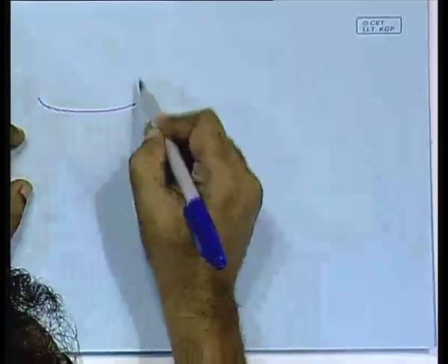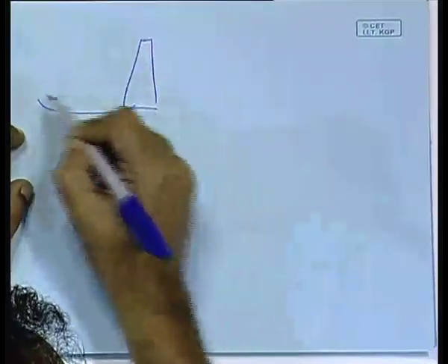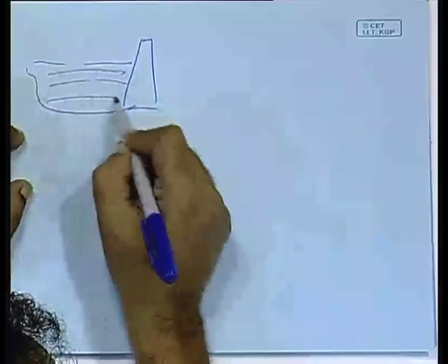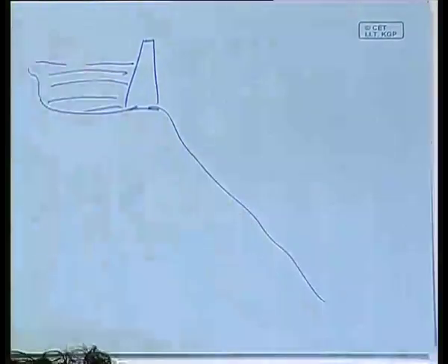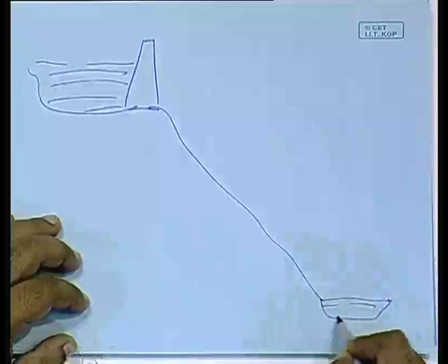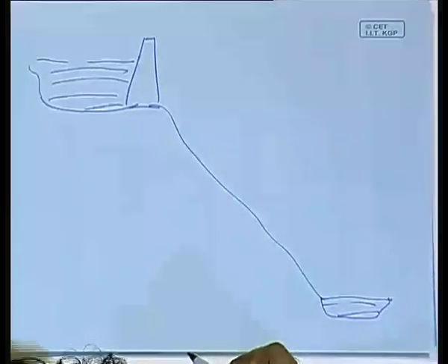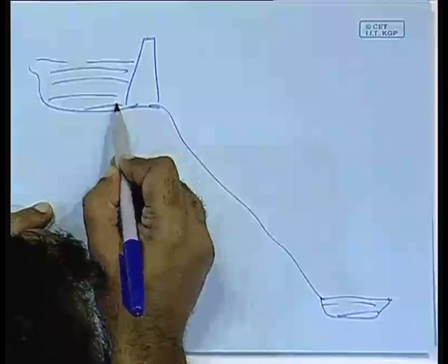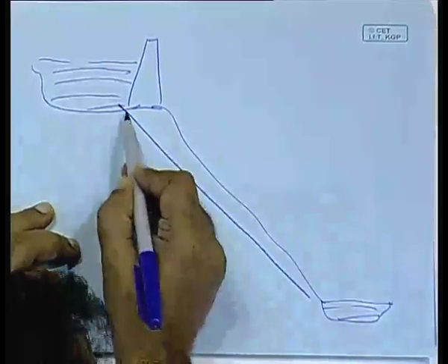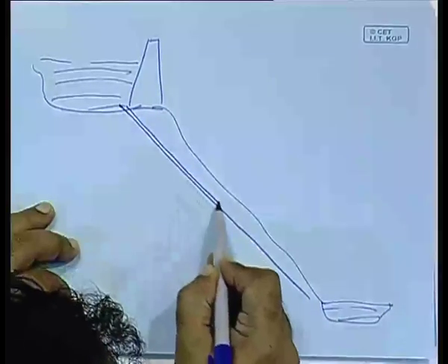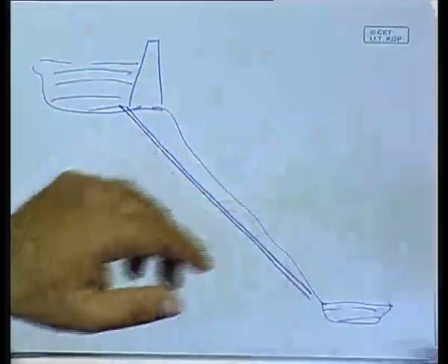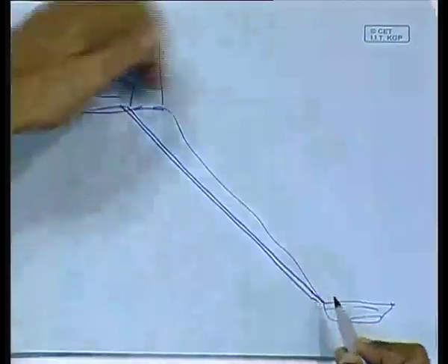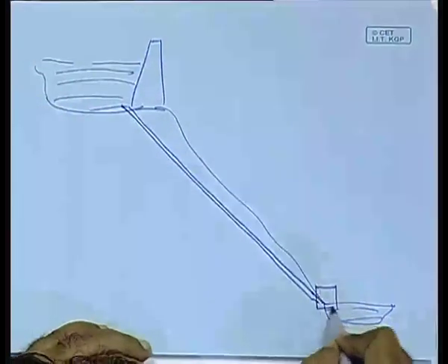Okay, before we end, let us again look at the structure of a normal power plant. There would be, in the upper reaches, some kind of a reservoir. So here you have the reservoir, and there should be a downhill slope, and here there will be another reservoir. And there should be a penstock going through. In most cases in India, in medium sized power plants, the penstock goes through the hill. That means it's inside the hill, it's bored inside the hill. In some cases it's outside, and here there should be the turbine.